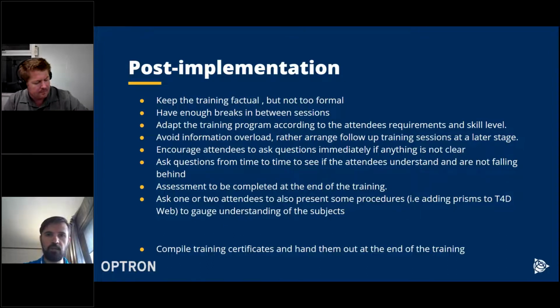Mm-hmm. Another one was about the types of power. You showed some solar panels earlier on. Is that the most common type of power for monitoring, especially I guess for total stations, but maybe it's different for other sensors? Actually, the most common that we find is to have a permanent electricity supply. It's also the easiest one, because we still install backup batteries. So if that electricity supply goes down, the backup battery will continue running.